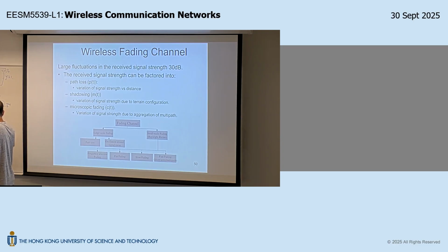This time encapsulates the mobility, the time variation. The time variation, of course, as I mentioned, is driven by mobility of the physical objects, either the mobile receiver or the environment or the scatterer, okay? This second dimension is to model the so-called multipath. Okay, so how many paths arrive from the transmitter to the receiver? What will be the delay, response, etc.? So this is the multipath dimension.